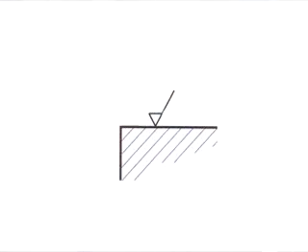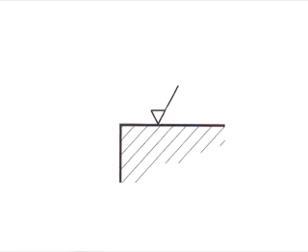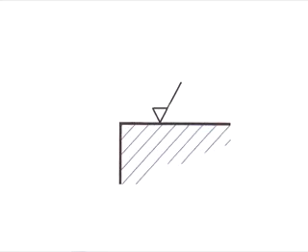Another thing that we find on drawings are symbols, and there's all kinds of symbols. We can take as an example a surface finish symbol or a texture symbol. There are welding symbols and all kinds of symbols. So here are a few examples of some symbols that you can find on drawings. Here's one that we find on a lot of my drawings, and it indicates that the surface that it touches needs to be machined.